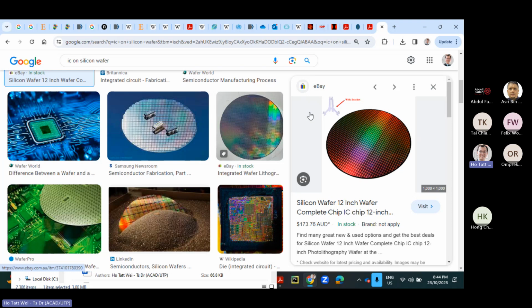And this is why nowadays when you make repetitive devices, like RAM and all that, typically people will draw a few extra rows and columns of the device, but they will not actually use them. They just draw them and include them in the chip. Let's say you have a row of adders. If you want that adder to be very consistent, you have a few other rows of adders to the left and the right. The additional adders are actually not functional. They are just created to create a very stereotyped environment around your transistors, around your logic gate, so that you can control the process variability. So you are using additional chip area to control the process variability. You're creating redundant structures, redundant logic that probably is not used, all for the sake of the space where the logic is used, to make that more reliable.